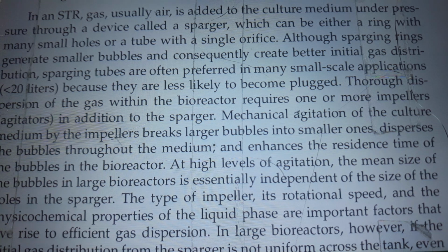And so thorough dispersion of the gas within the bioreactor requires one or more impellers or agitators in addition to the sparger. Mechanical agitation of the culture medium by the impeller breaks down larger bubbles into smaller ones, disperses the bubbles throughout the medium, and enhances the residence time of the bubbles in the bioreactor.